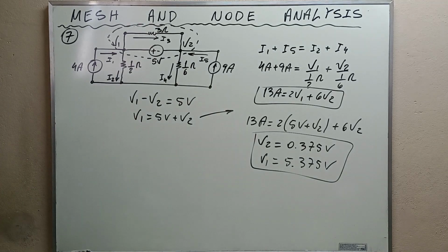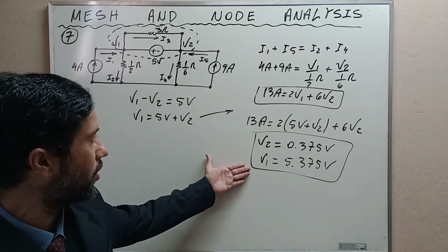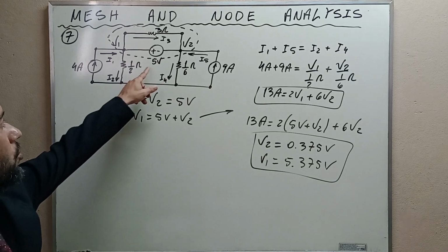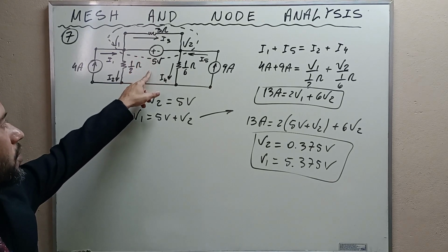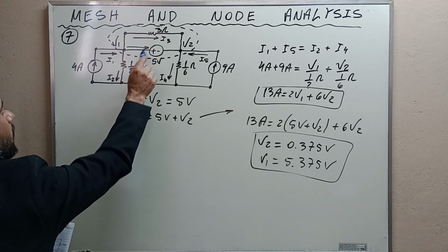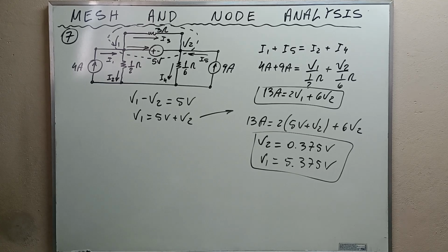And this is the solution of the exercise. Let me remember the exercise when it asks to calculate the voltages at nodes V1 and V2. And this is the answer, okay? This is the solution of the exercise. We used a supernode here because we understood that we could not model the current that flows here, okay, because there is no resistance, then we used a supernode.